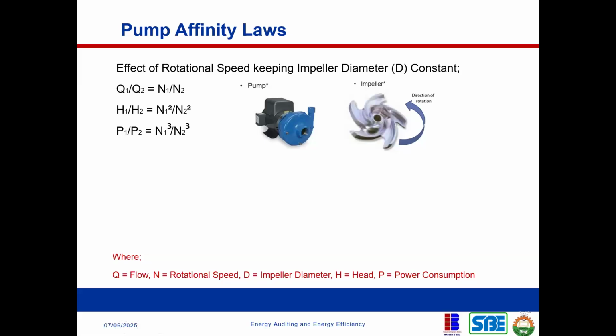So now let us look at affinity laws. Remember when I talked about impeller diameter, impeller speed, and energy consumption. A fine scientist has been able to put this together, and it's known as affinity laws. Affinity laws are the laws that help us to understand the relationship between impeller diameter, the speed of the impeller, the height of pumping, that is the meters that you want to pump, and then the quantity of water that you can get, or fluid rather, because it can be anything.